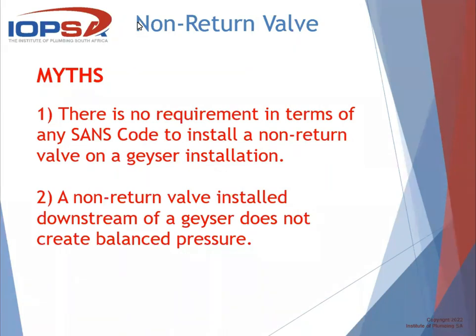But if it's a pumped system, so it's not a thermosiphon system, the panel is higher than the tank, then you have to put some sort of a non-return valve in next to the pump so that the reverse thermosiphon doesn't occur, because at night when the panel is cold and the water is hot in the tank, all that hot water wants to travel to the panel and it will dissipate the heat, and that reverse thermosiphon will occur. So you have to put a non-return valve in there. So you need to choose that non-return valve in conjunction with the power of the pump.